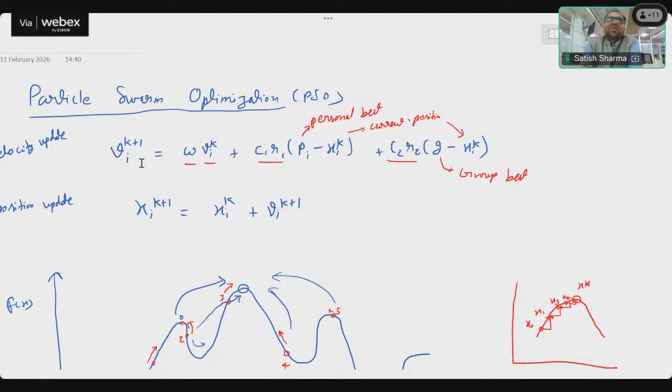What ChatGPT did was, instead of the equation we used to write, Pg minus Pd equals power flow, where the power flow formula was Vi Vj Yij cos(theta ij minus delta j plus delta i), this was the power flow formula for our ACOPF. It provided me the formula Pg minus Pd equals Vi Vj. Now how can the power be equal to the voltages? But it gave me the code.